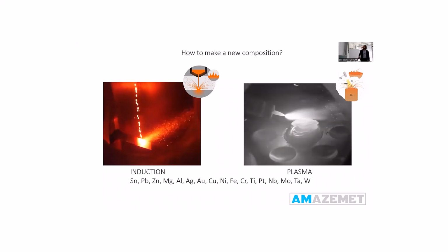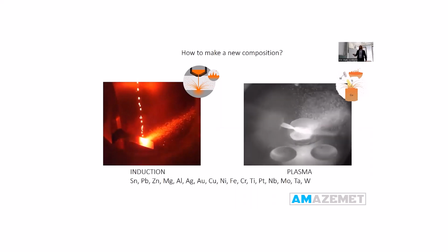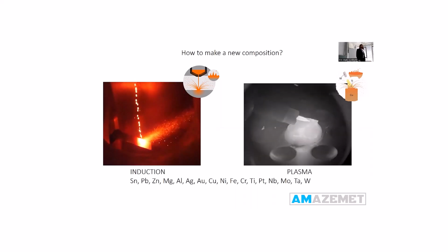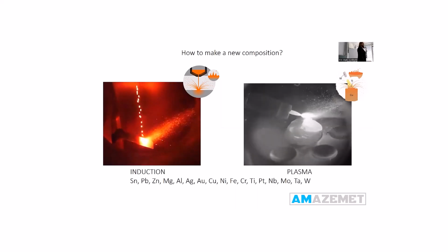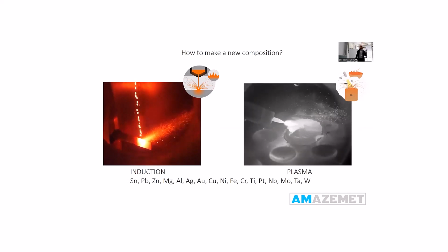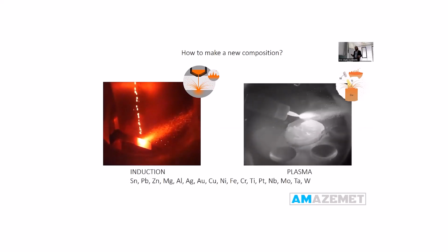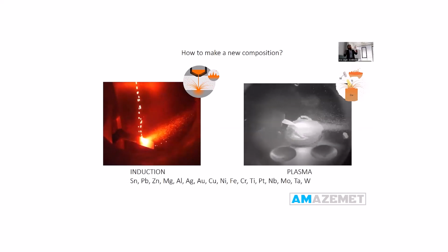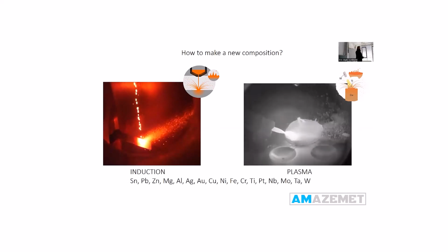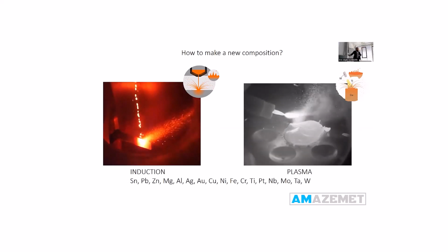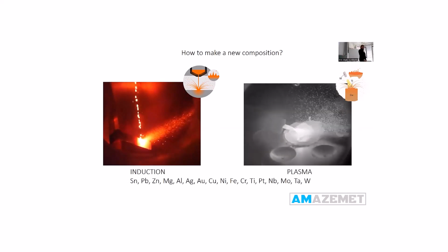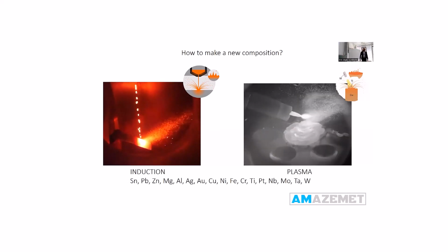So basically, again, the commercial part. What we're actually able to do is to create this paint in whatever chemical composition we are willing to have. In a small system, one day I have an idea, okay, let's add some yttrium to get those oxides and increase our glass forming ability. Or the other day I have an idea, okay, let's add niobium to change the mobility of atoms in the melt.